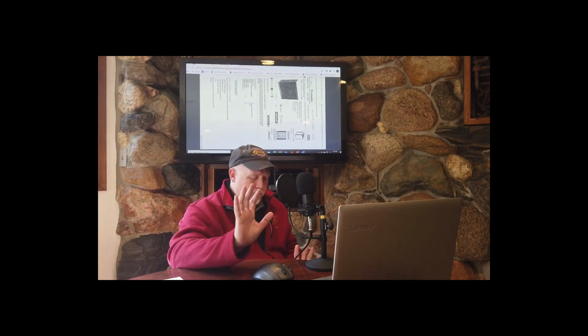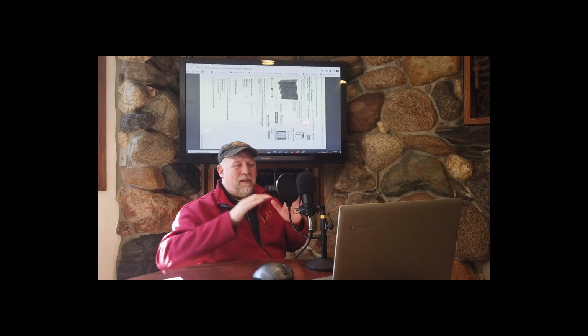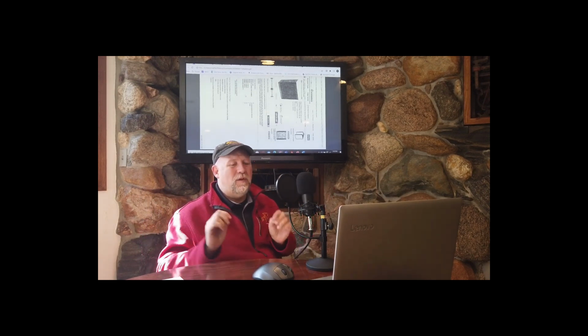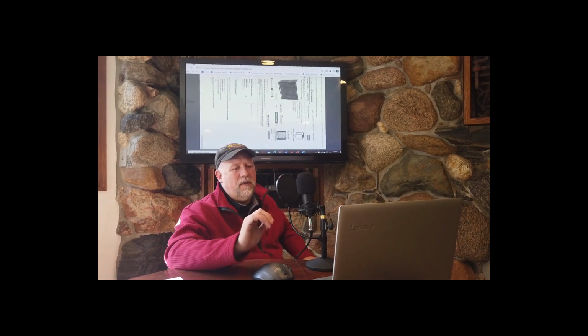So, a way to capture more dust and dirt: you slow the air down as much as possible and give it as much filter media, as high quality media as you can, to catch and capture the particles.